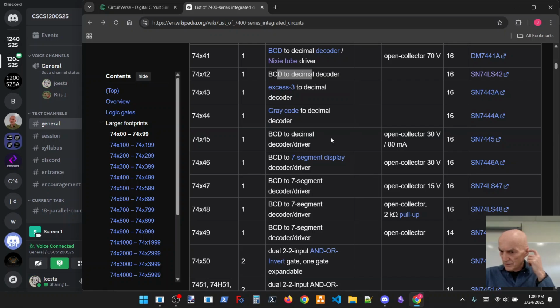You go from 1 to 2, the ones place and the twos place both change, seemingly at the same time. We're like, I can't allow that. So is there a pattern we could go through where we could hit all the different combinations, but by only changing one at a time? Well, spoiler alert, the answer is yes, and that's what Gray code is.